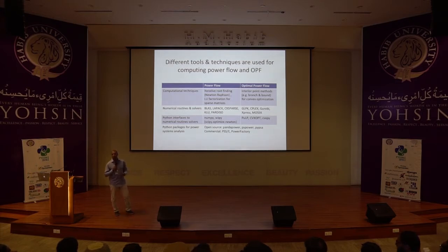And then there are the actual application-level libraries, if you just want to solve a problem like I do. I just put it into either Panda Power or PyPower or Matpower or something, open source usually. Because it's open source, it's free, you can look at the code. A commercial solver like PSS/E, which is used in NTDC or in most power companies, will cost you $100,000 a license, okay? Whereas the maths is actually the same.